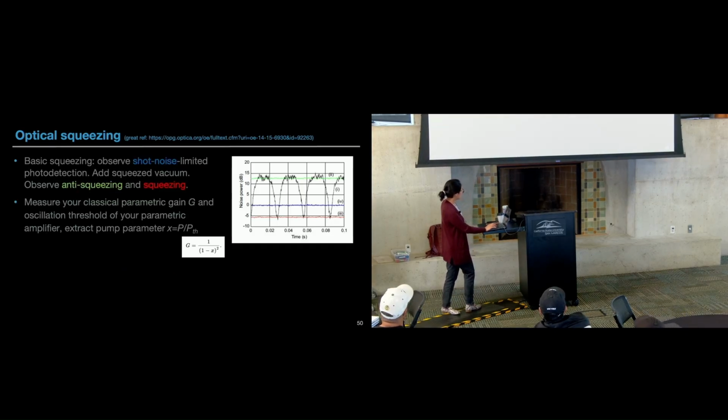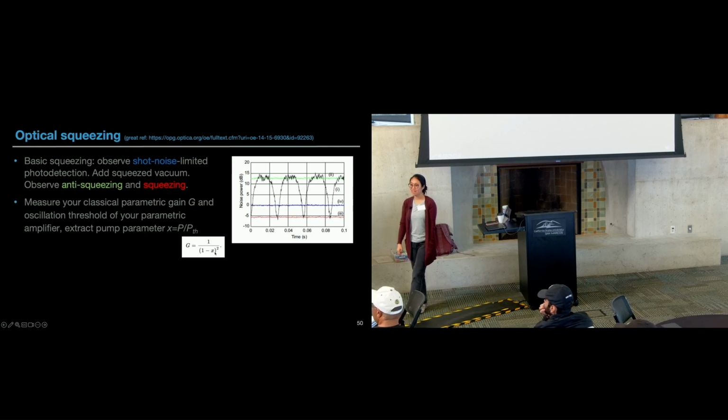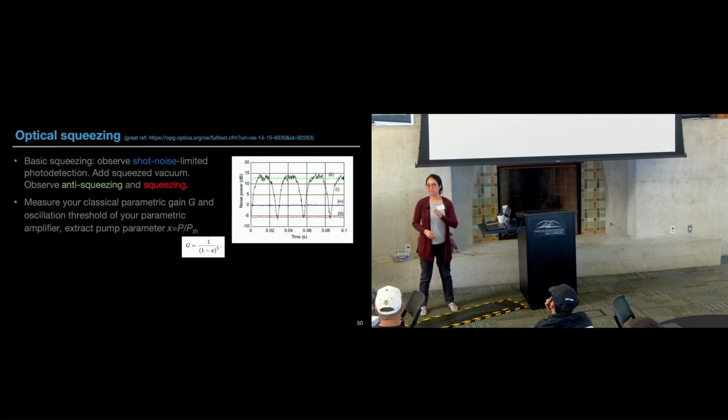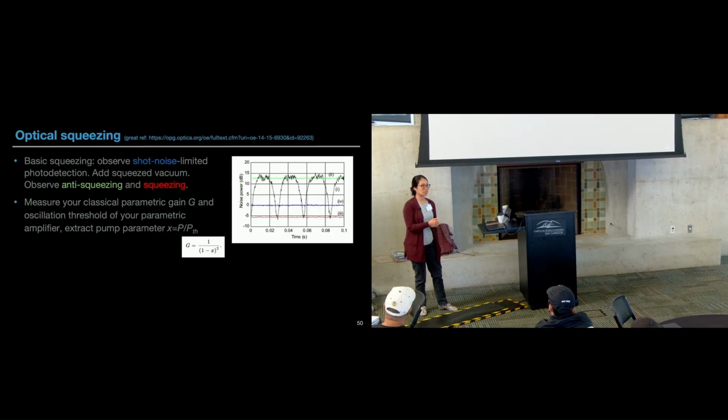Why is it like this? Okay, then what we would typically do is measure how much nonlinear gain I am driving. Yeah. I have a question. Yeah. From an experimentalist, what knob are you turning? The relative phase of the local oscillator compared to the pump light into the parametric oscillator, parametric amplifier, which usually amounts to a demodulation phase on a signal generator or something like that.